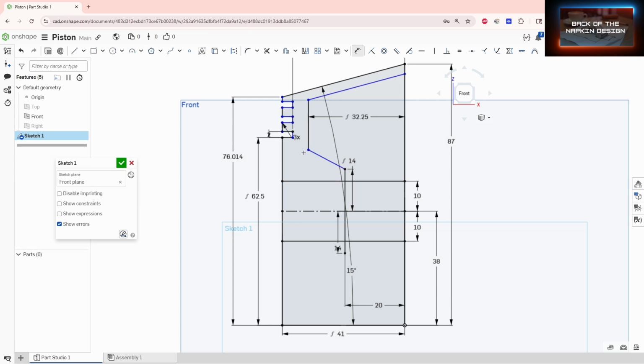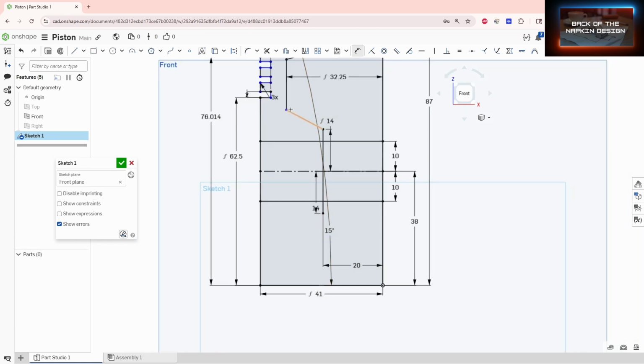And I don't have this dimension. Alright, not a serious issue. And I don't have a thickness for this. It's missing on the print. We're going to go by eyeball. So I'm going to click here, click here. Let's do 3 millimeters. Let's create a line. Using this line, pulling it down. Dimension from here to here. Let's hit D, here to here. Pull it down, and I'm seeing, I think it's 73 divided by 2.